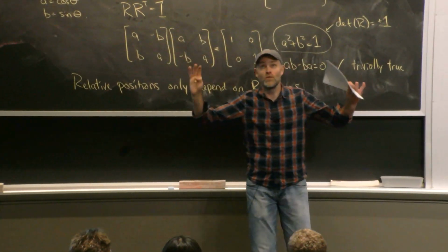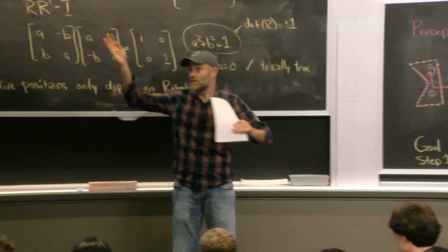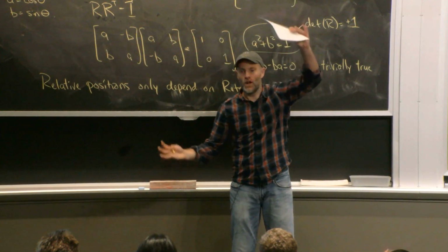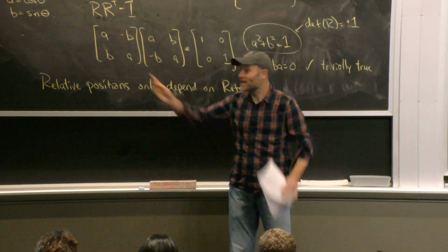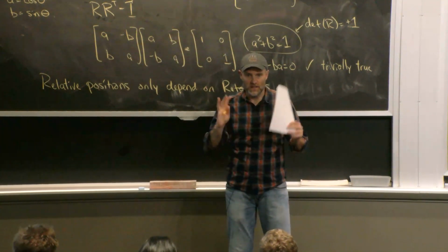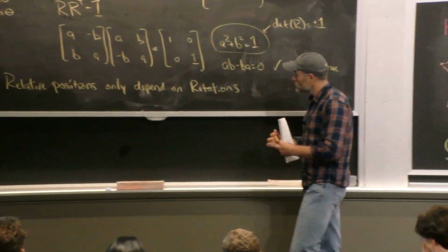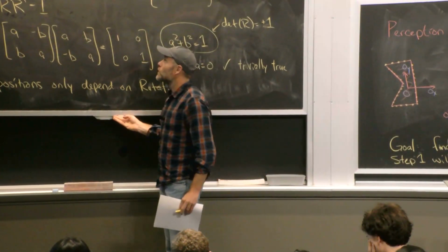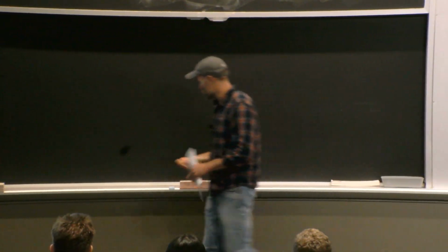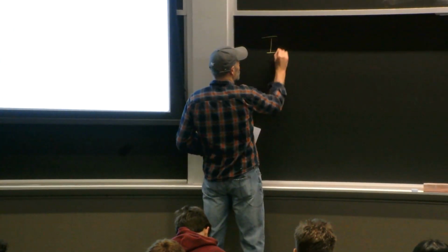If you know the basic picture of the geometry of the SVD, it's about finding the coordinates. You warp it to the circle, you rotate it, and then you warp it back. That warping to the circle is exactly the warping that happens when projecting onto the unit circle. So it turns out to be exactly related to the SVD. Equipped with that, we now have the most important algorithm for geometric perception, which is the iterative closest point.